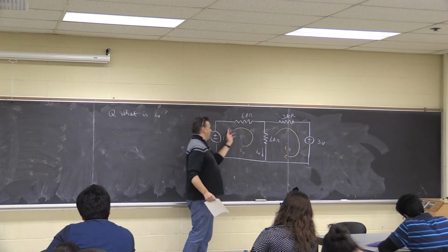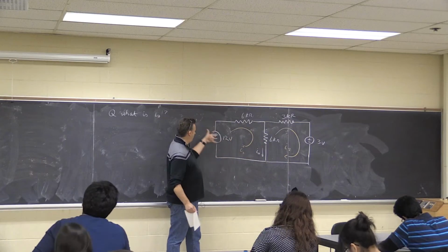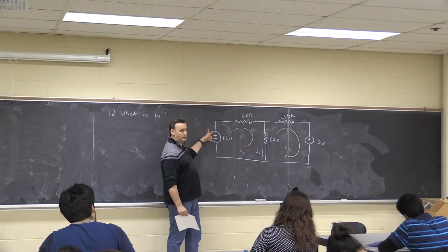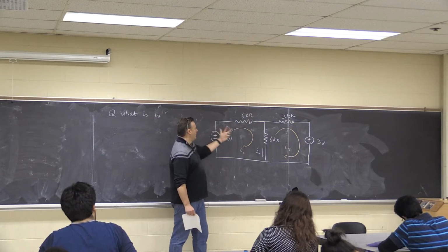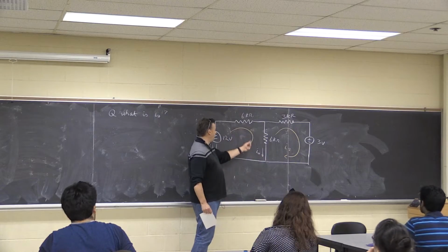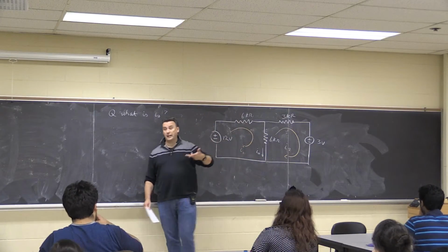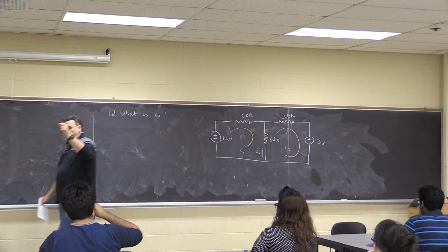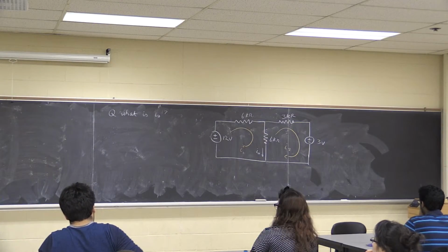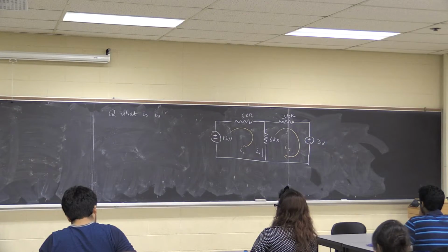It's relatively easy to say, if I go around this loop, I'm going to have a voltage source here, so I know the voltage change at this point. So it's going to be 12 volts. I know the voltage drop across here because I know the loop current and I know the resistance, so I can work that into a voltage. So I can walk around the loop with the loop current, and every time I go through a resistance, I know what the voltage drop is because it's the sum of all loop currents in that branch.